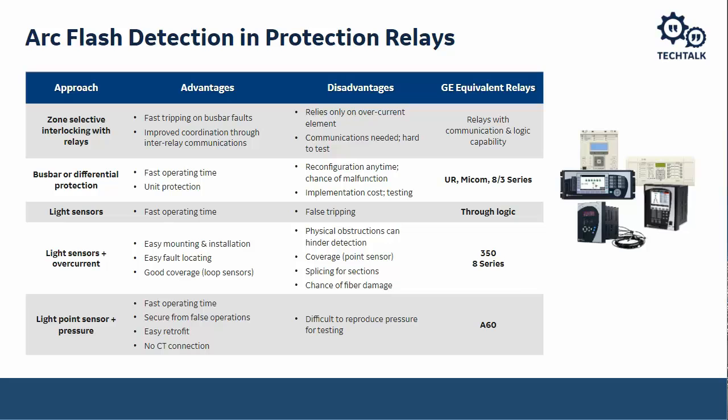Bus bar differential protection, this is nice, it's fast. The cool thing with this is it's unit protection, so there's no coordination required between anything. Depending on how your switchgear's laid out, the cabling may be somewhat of an issue.